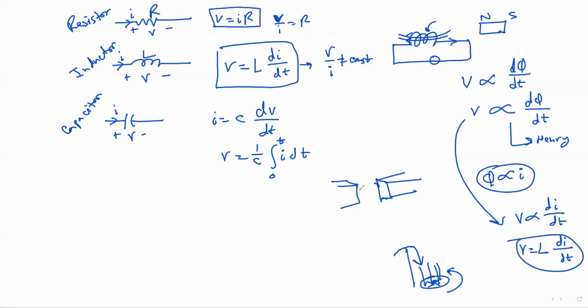Where does rotation come in the principle of producing electricity? Let's see how. Let's not draw the 3D view, but okay, let's draw. If you have a single loop coil of wire, and you have North Pole and South Pole here, then magnetic flux passes through the coil.